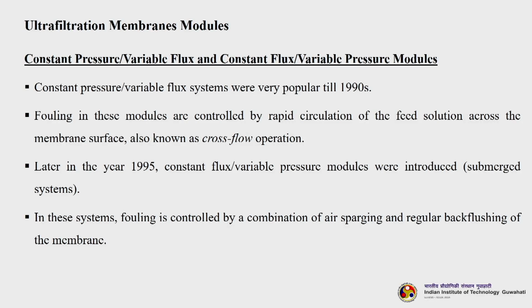Now, let us understand the different types of modules. We have been discussing membrane modules in general, and we have discussed the membrane modules in detail in the RO systems. Here we will discuss them just briefly, because most of the module configurations are the same, however, their operating features are different. So, instead of understanding the modules and their operation today, we will try to understand the operating parameters for these particular modules, what can be done and what cannot be done with respect to ultrafiltration.